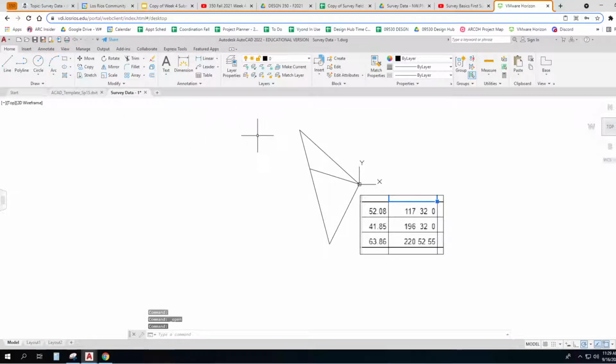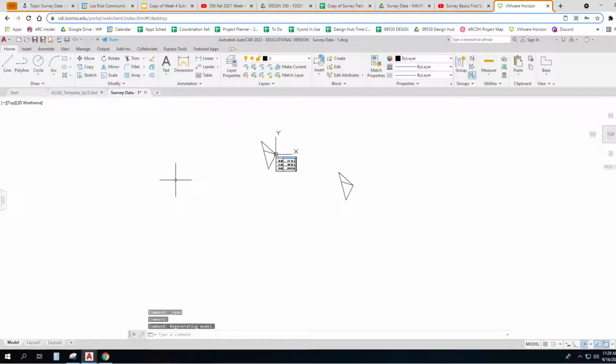If I'm over here and I'm just doing stuff and I go, I want new layers, I want new dim styles, I want new line types, I want new layouts, how do I get those things? Well, when I'm in my drawing, I type DC.